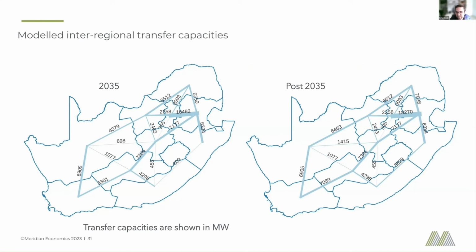Whereas often you're getting these spikes in power for short periods of time that happen often, and each time the pumped storage can only go to, say, one gig. If it's a 1 gig unit but it has 20 gigawatt hours of storage, you can only charge at 1 gig each time. Whereas you have battery storage coming in with 4 hours, so basically a 5 gig battery would have the same gigawatt hours. So you can grab that extra energy.